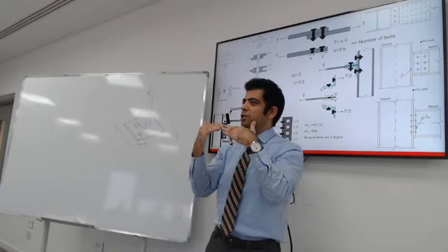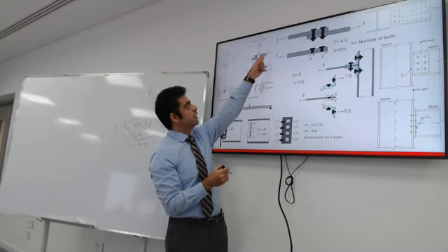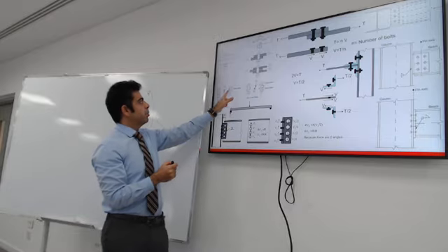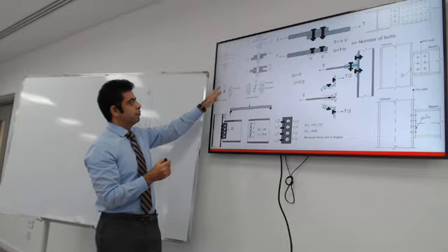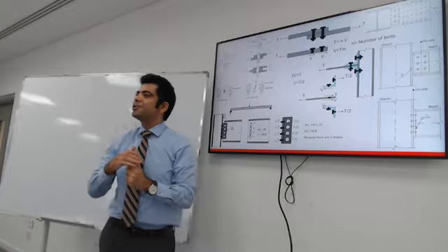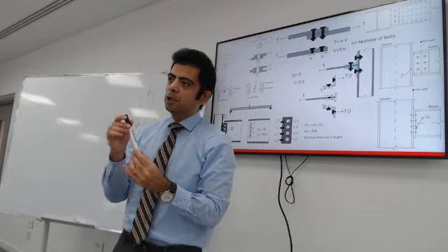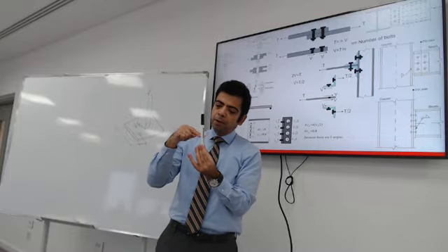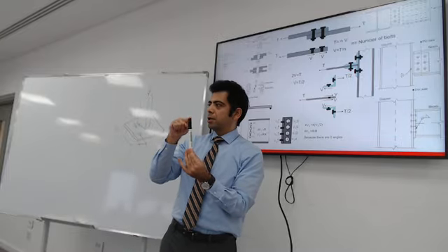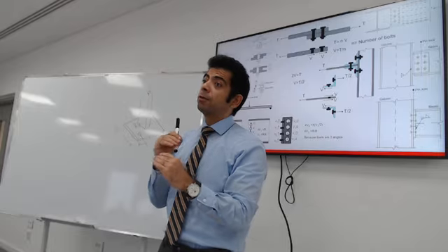They're trying to apply shear. Can you visualize how this plate and this plate are applying two opposite forces trying to shear off the bolt? That's the direction of shear. Shear is perpendicular to the longitudinal direction of the bolt. You can have single plane shear or double plane shear.